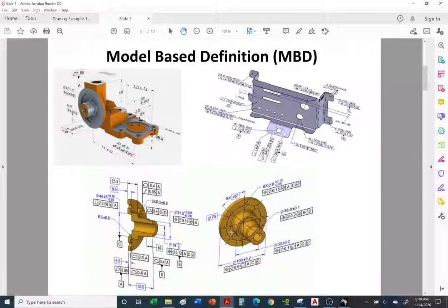Now, if it deviates from the tolerance given in the documentation, then they would have to attach it to a note, or in this case, this dimension. They're telling us, hey, this shaft, this diameter, this is millimeters, is 50 millimeters, and you can be off by plus or minus 0.2. So the diameter of this shaft here can be up to 50.2, and it can be no lower than 49.8. Okay, so this tolerance deviates from the tolerance in the notes.